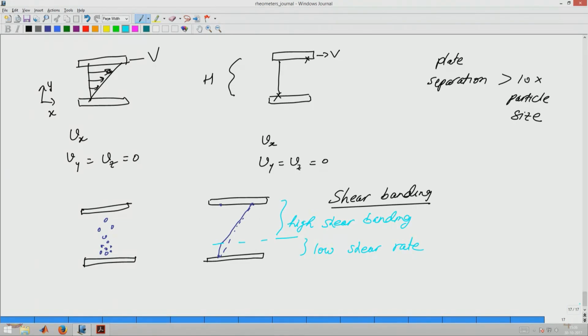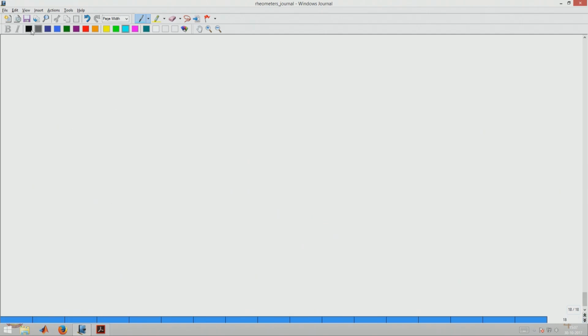But in other case, if for settling slurries itself we need to have some estimate of properties, then we must do such experiments, but we have to be careful that while analyzing our data we must know that the overall flow is not really what is assumed, which is a linear velocity profile. The best way to look at this is through flow visualization, and again in this case what we can do is we take the overall material of interest, and we again put one small set of particles, and using laser and scattering we can follow how these particles are moving.